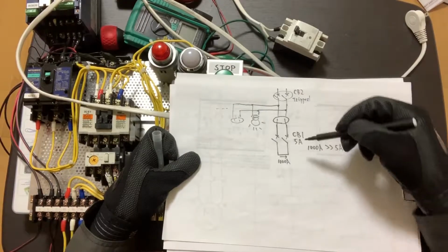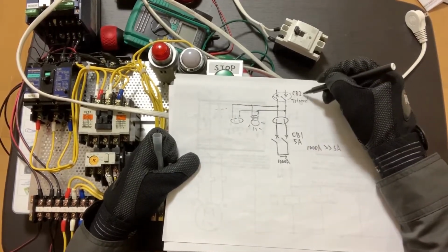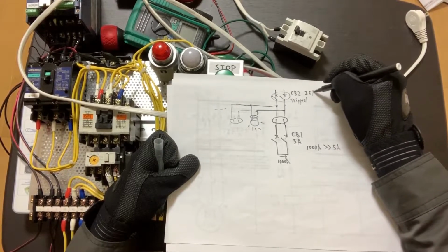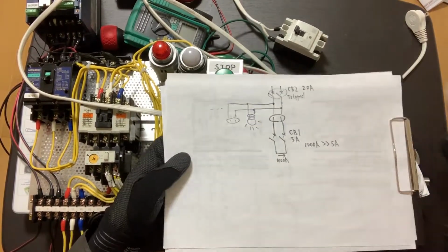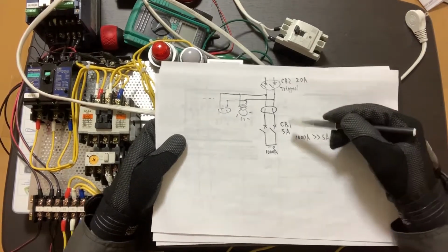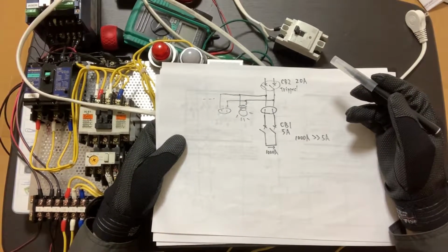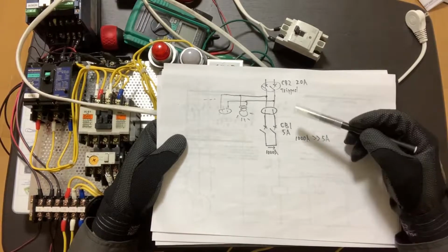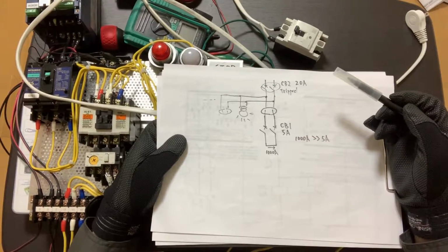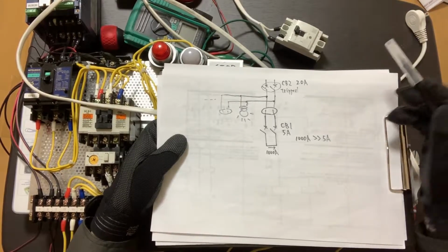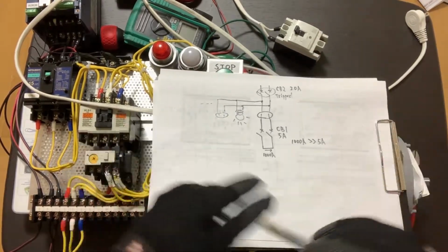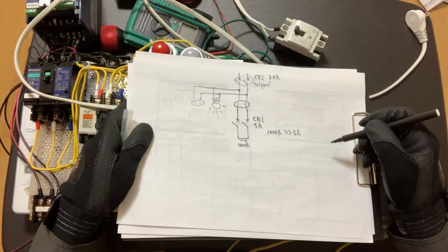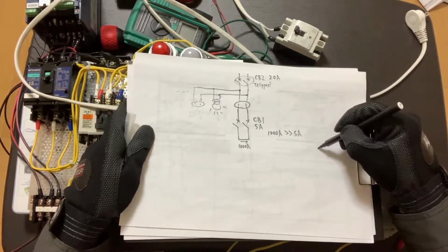I confirmed that this circuit breaker 2's rated trip current is 20 ampere. I guess the 5 ampere one tripped first because 5 ampere seems more sensitive than 20 ampere. Let's think. So if this